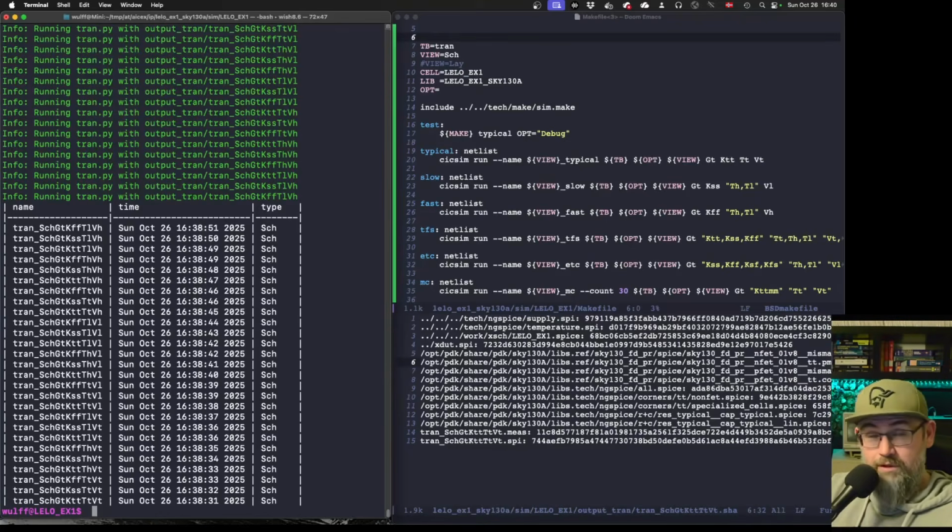And within a wafer, you can also have different transistors, because the lithography of just developing the circuit may have different patterns depending on where you are on the edge, depending on where you are on the wafer. All this means that we have to check what's called corners. So a fast transistor, a slow transistor, and a typical transistor.